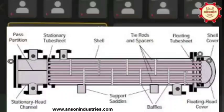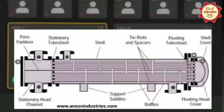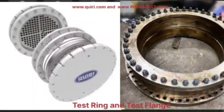My question is, in a heat exchanger we generally use a test ring and test flange. Now there is a condition where the client has mentioned he wants the test ring and test flange in forging condition. Generally it's not an operating condition part of a heat exchanger, so we make it from plate. The exchanger type is AES, floating head type, so it requires a test ring and test flange. But normally we make the test flange with plate, not forging.